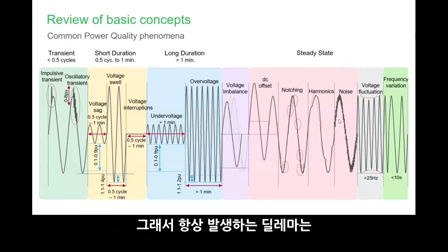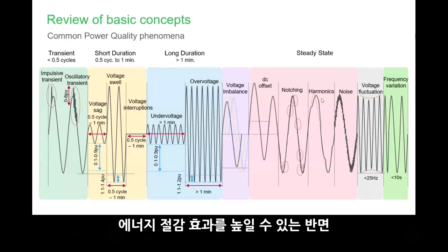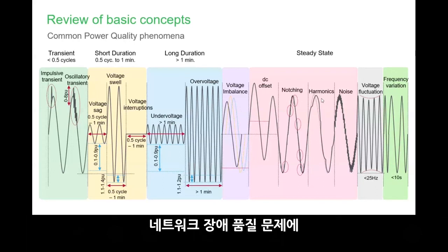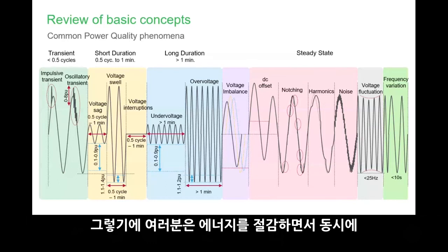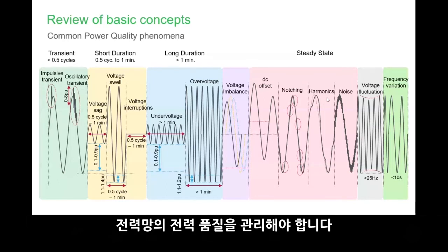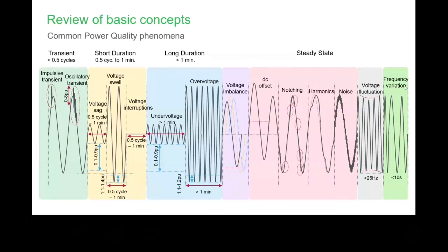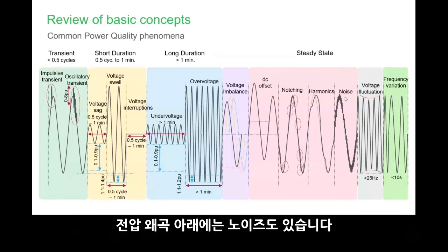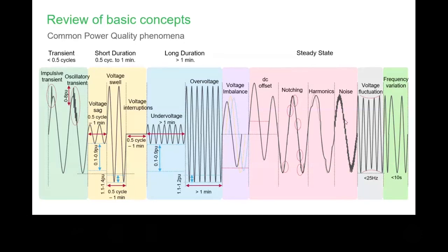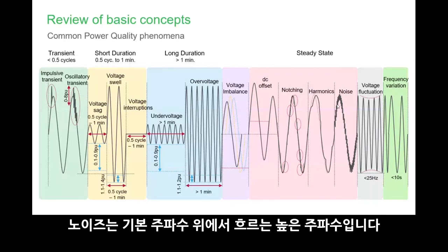Okay, so there is always a dilemma where you do a lot of energy savings, but at the same time you're contributing a lot of power quality issues into the network itself. So on one hand you do energy savings, on the other hand you have to take care of the power quality in the electrical network. Okay, and under the waveform distortion, we have this noise. Noise is talking about high frequency riding on top of the fundamental frequency.